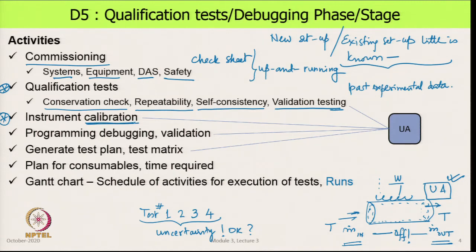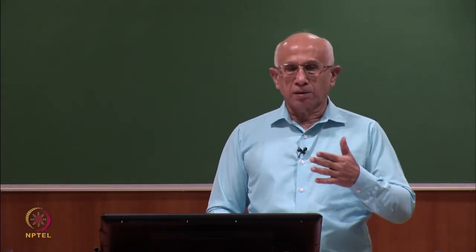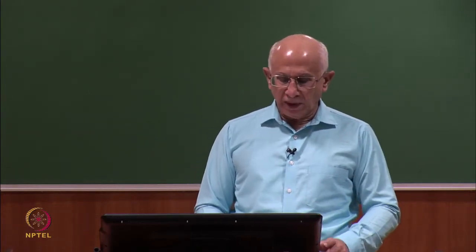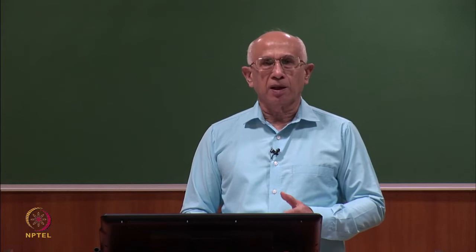So, this is a very important part, and there is very extensive literature on the science of calibration, the techniques of calibration, and ultimately what is the best possible result that one gets. We will come back to this a little later on, where we have primary standards which give the most accurate values anywhere in the world, then transfer instruments and like that. We never use the top quality instrument, which is the standard instrument, simply because it is too expensive and practically not possible.